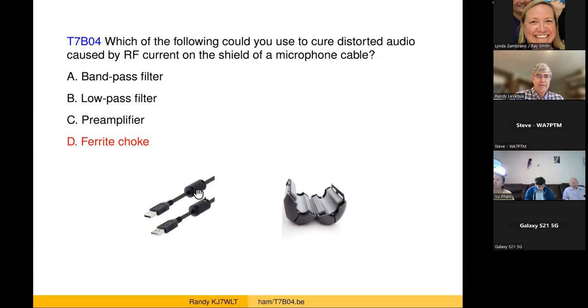You may have some cables like these USB cables shown here. You might have power cables on your laptop or on other equipment that have a built-in ferrite choke. If you've ever wondered what these round cylinders close to a power outlet on a cord are, that's a ferrite choke. You can also buy ones that look like this that you can snap onto wires. You can get bigger ones that are rings of iron that you can wrap a cord through several times. On all sorts of cables, on antennas, on power lines, on microphone cables, it's often a good idea to put a ferrite choke in to filter out some of the current that can move on the cable itself and create radio waves that can interfere with what you're trying to listen to.